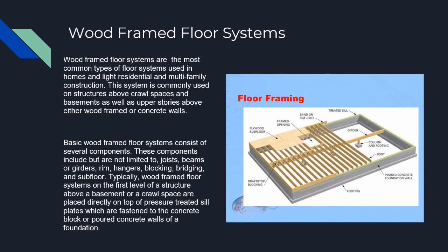Wood-framed floor systems are the most common types of floor systems used in homes and light residential and multifamily construction. This system is commonly used on structures above crawl spaces and basements, as well as upper stories above either wood-framed or concrete walls. Basic wood-framed floor systems consist of several components. These components include, but are not limited to, joists, beams or girders, rim, hangers, blocking, bridging, and subfloor.